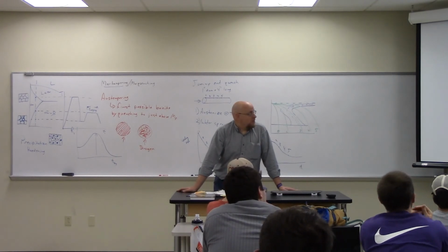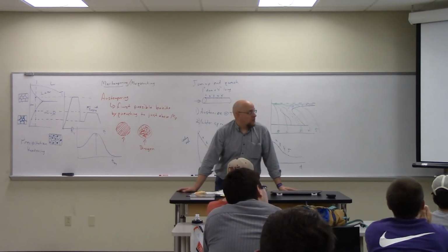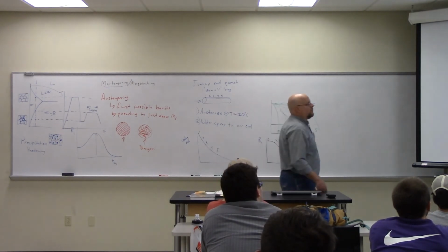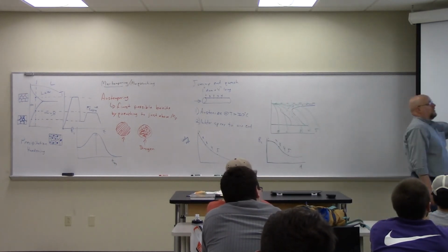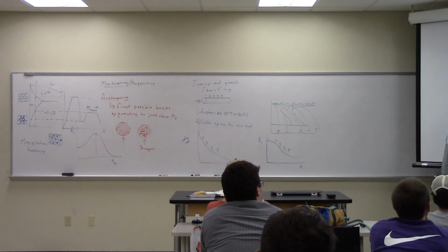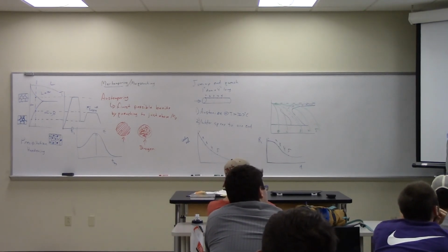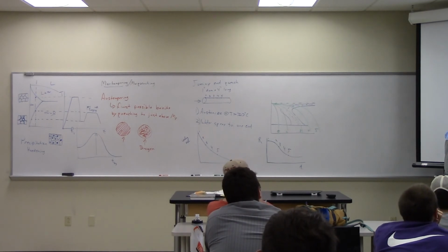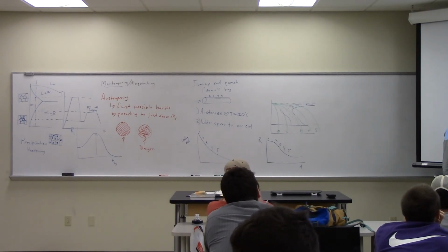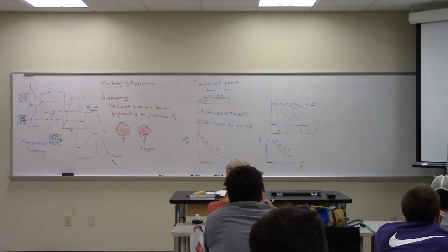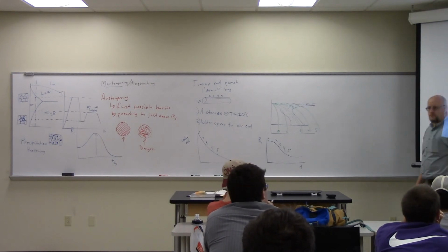And remember the observation, the approximate nature of using an isothermal diagram to represent a continuous cooling process. After transformation initiates, like I said, this whole thing is supposed to be down and to the right. The way that we consider it is that we identify the place where it starts to transform, and then unless we quench from there, we consider that that basically forms all of that material. Kind of an isothermal approximation.